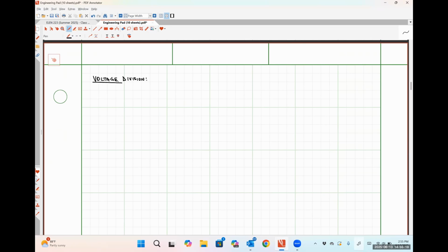And so this derivation is going to look incredibly similar to what we did for defining how resistors combine in series until the last couple of steps. Okay. So I'm going to start with a network containing several resistors connected in series that is part of some larger circuit. So here's some resistance R1, some resistance R2, all the way out to some resistance R sub n, like so.